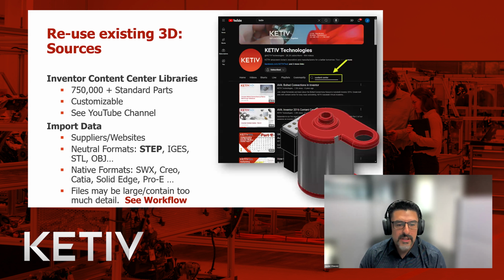In fact, last week we spoke to a customer and they sent me their design, and it was 1.2 gigs. It was gigantic, and it shouldn't have been that big. It was complex, but it shouldn't have been that big. And it's because they purchased a generator from a different vendor, and they get every nut and bolt, every internal component with it, and they haven't really changed it so that it's lighter and just meets their usage needs. They just need to know a part number and an envelope, right? How much space does it take up? Maybe how much it weighs, right? So that's the next part of this.